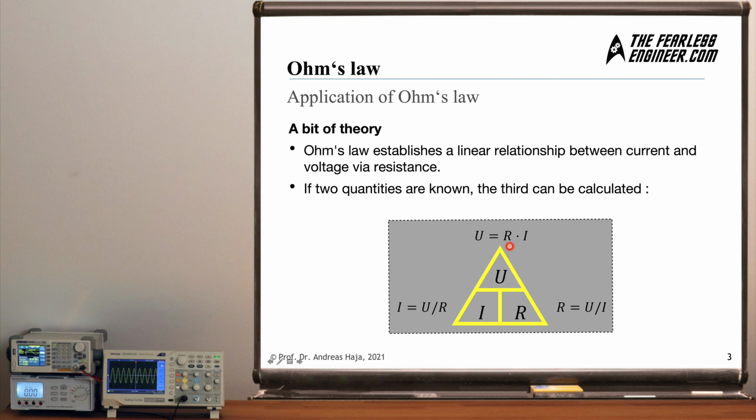For a proper resistor used in electronics, we can assume ohmic behavior, which means R is constant over all values of current, at least in moderate dimensions. There's going to be some point when the ohmic behavior of a proper resistor breaks down, when we make the current too large, but for most values up to a certain level, we can assume ohmic behavior. But there are other materials for which this property does not hold, for example a light-emitting diode or a PTC resistor.